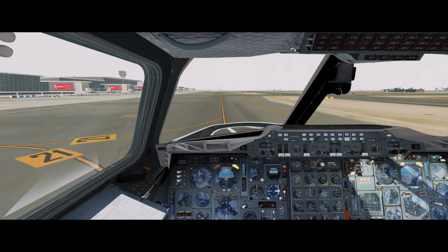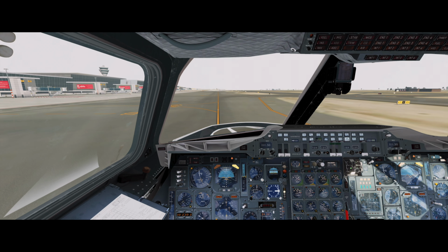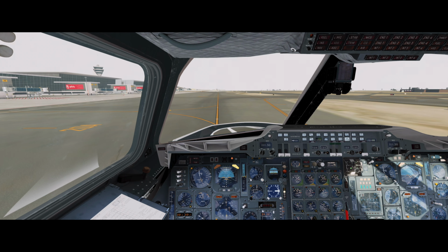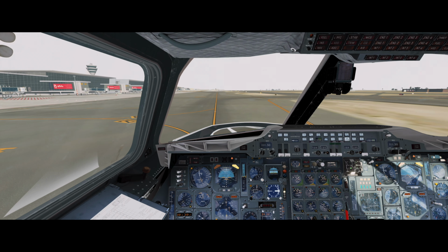Taxi checklist, visor and nose. Down 5 degrees. Brakes. Have been checked and are normal. Flight instruments. Checked here, no flags. Flight controls, EFC. Yep, they're all in blue and the light is out. Trims. 2.5 set for takeoff.